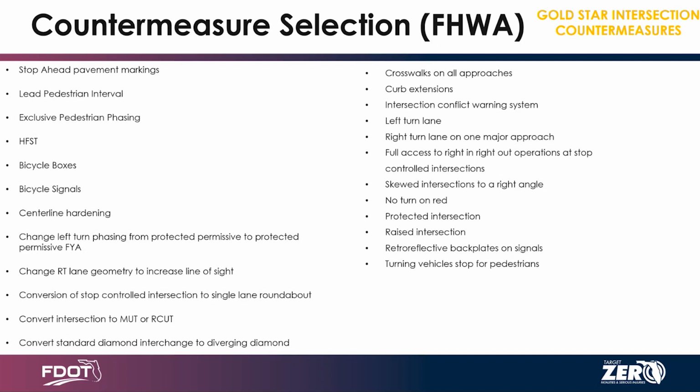But when you start to get multiple, if we think back to Tuesday's conversation, that's when we start to get to multiplying CMFs. When you're doing multiple CMFs, you need to make sure they are consistent in the type of crash they address and consistent in the severity of the crash that you address.